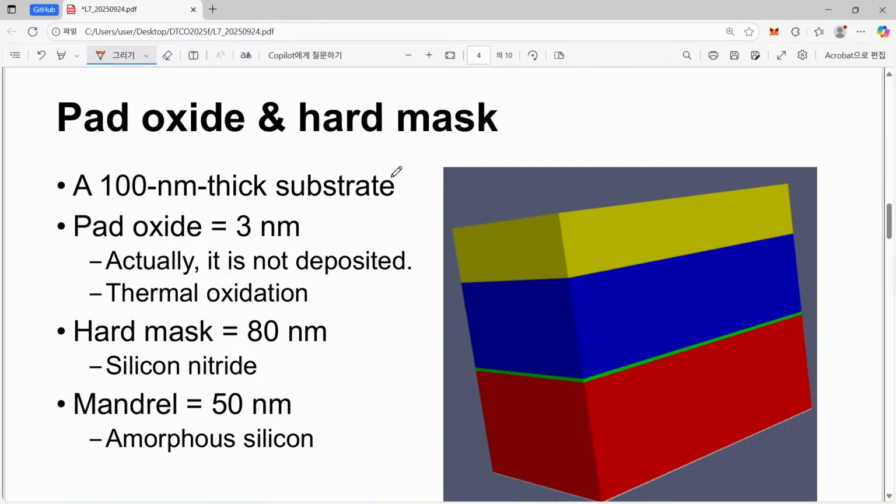Fabrication process. So first of all, we have to fabricate this fin structure, uniformly distributed fin structure. Do you remember our numbers? So fin pitch was 27 nanometer and the width of fin was 7 nanometer, and this fin pitch 27 nanometer is not directly achievable by certain lithography. I mean that of course when we use EUV, then it can be achievable.